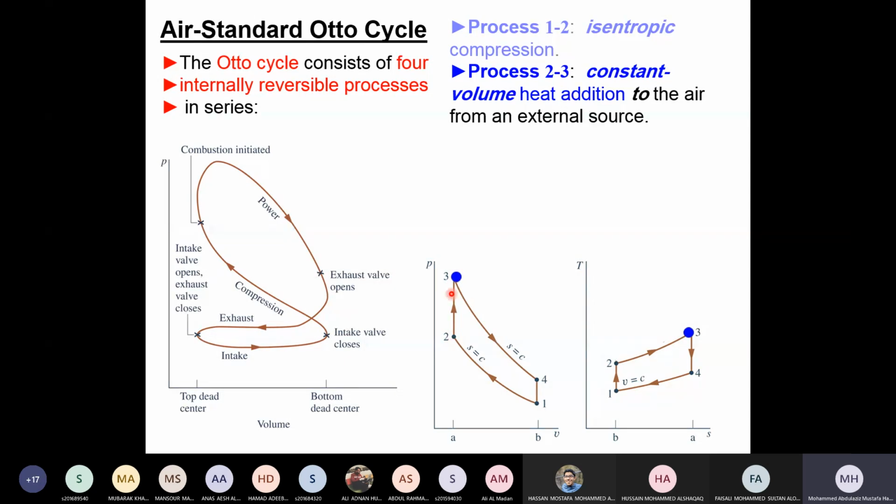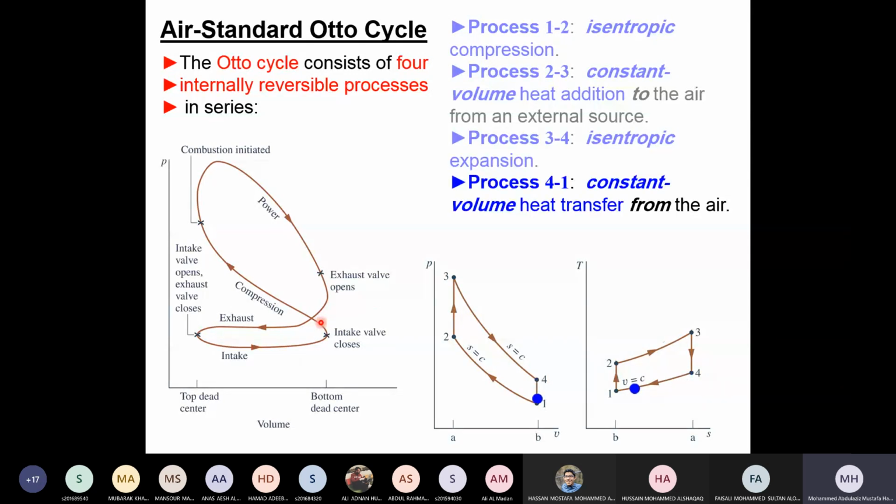You know that the work is equal to the integral of PdV, because now this is a system, a closed system. So now with this here, I can calculate the work under this and the work under this. Then I'm going to approximate this also as a constant entropy process. And then I can approximate this as, again here, a constant volume process.